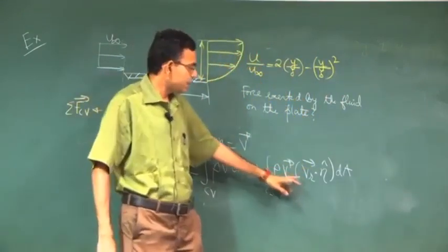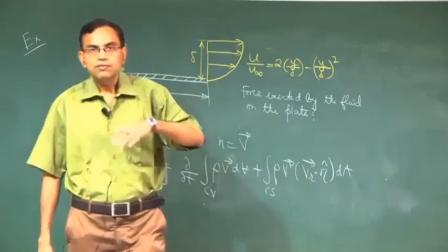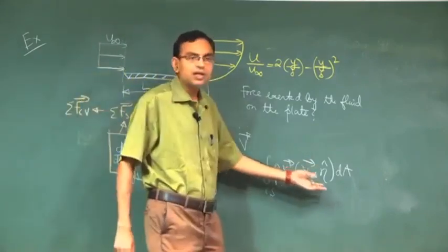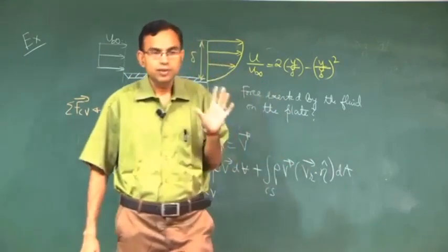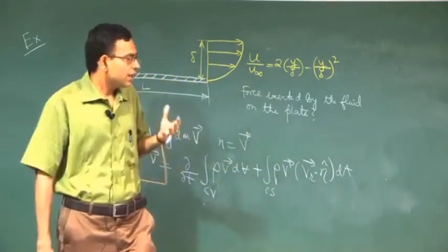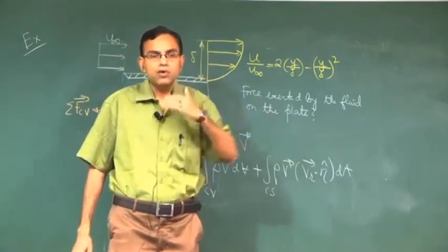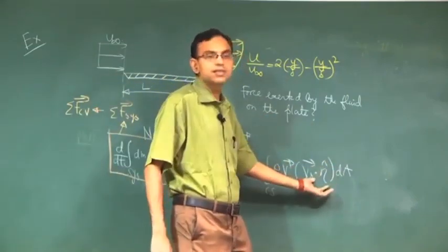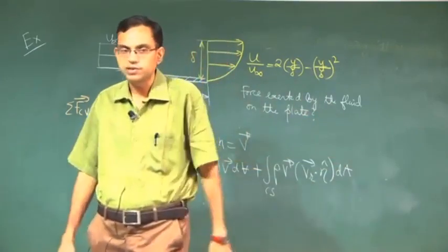Sometimes this is called the momentum theorem. In fluid mechanics, in various texts, typically at the undergraduate level this is not derived and is just introduced as a momentum theorem in most undergraduate fluid mechanics textbooks. But I believe that Reynolds transport theorem, being the most general one, no matter whether it is mass, momentum or whatever conservation, it is better to follow from that. I do not mind if this is called the momentum theorem, but it is fundamentally Reynolds transport theorem applied for momentum conservation.